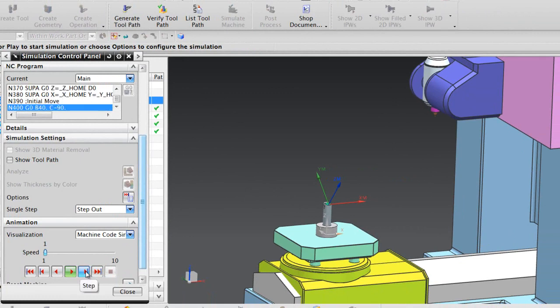Here we go, now we're getting into it. We rotate the B axis and the C axis. We then use CYCLE832. And then as we step farther, you can see the TRAORI. Using the G54, we're going to orient the machine coordinate system, orient the axes, translation and rotation, and then we begin actual machining.